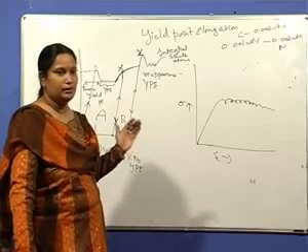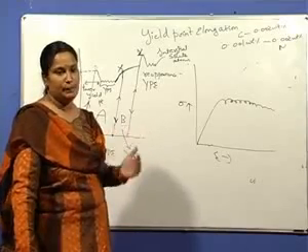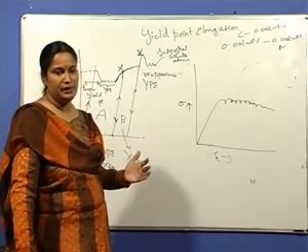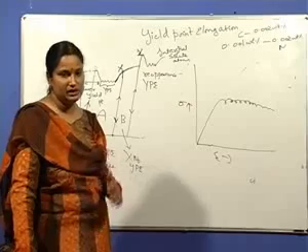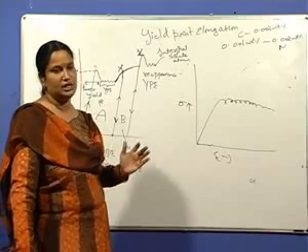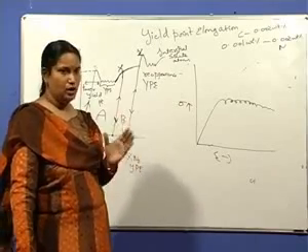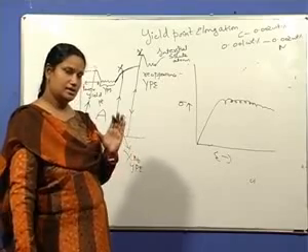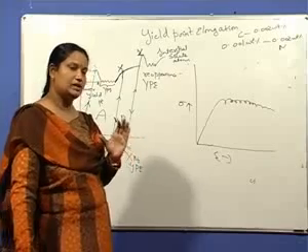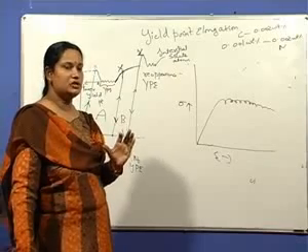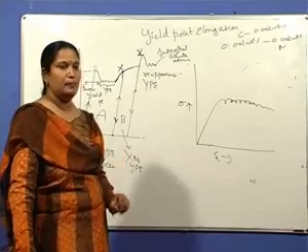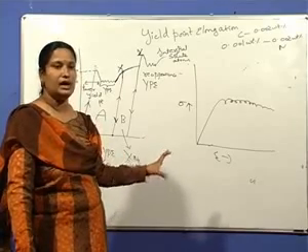And this is not beneficial for the case of sheet metal parts. Why? Because it gives a very bad appearance, a rough appearance. So this has to be eliminated. So to eliminate this yield point elongation, a small amount of cold reduction is given, that is cold rolling. That is also known as skin pass rolling or temper rolling. The percentage of deformation that is given is 0.5 to 2%, mainly to eliminate this yield point elongation.